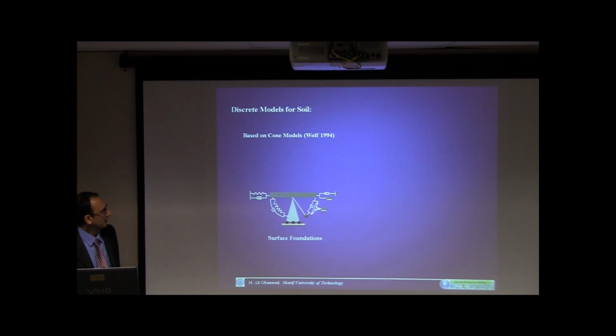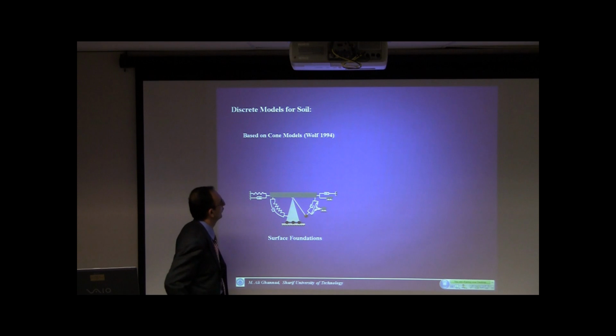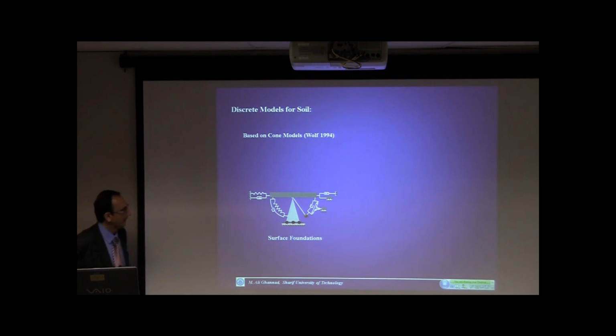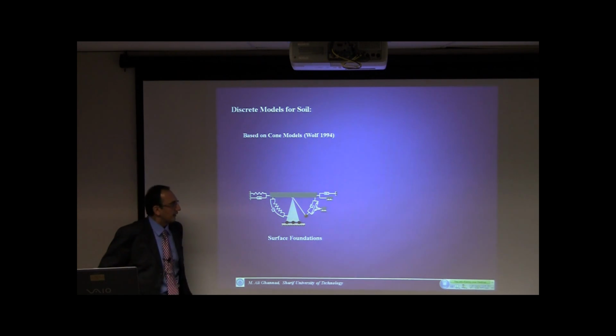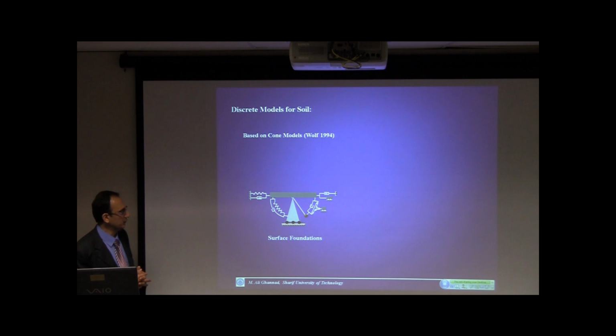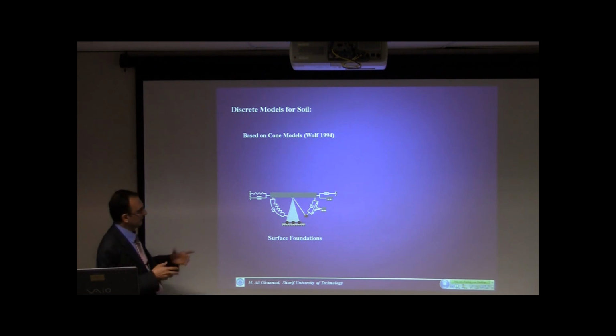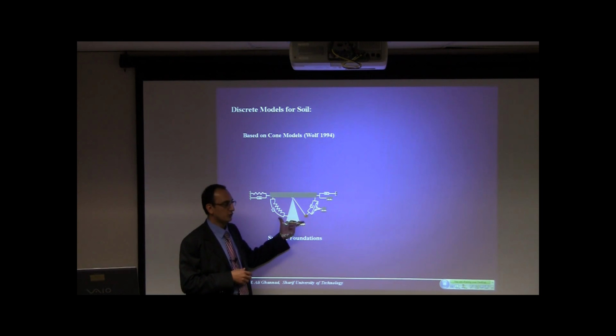For the model, here we used discrete models based on the works of Professor Wolf. Of course, when we want to work in the inelastic range, we cannot work in the frequency domain. So these kinds of discrete models allow you to work in the time domain, but consider the frequency dependency.